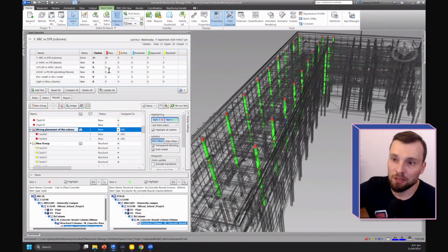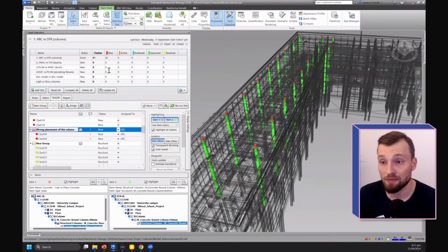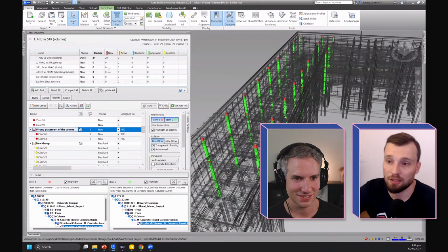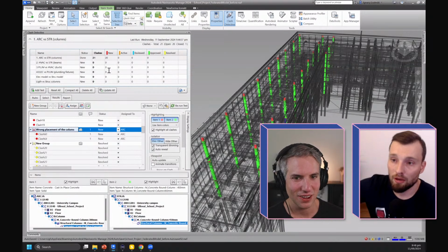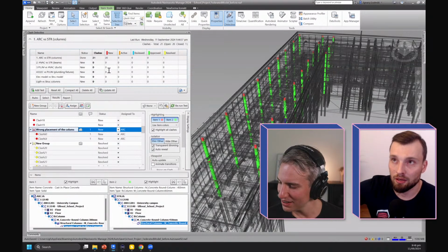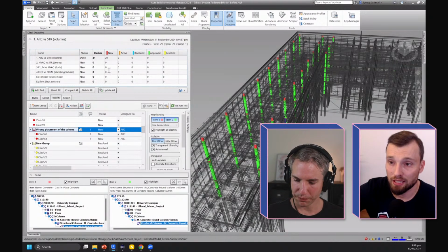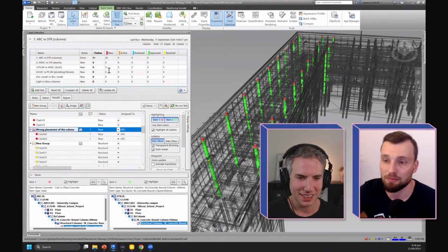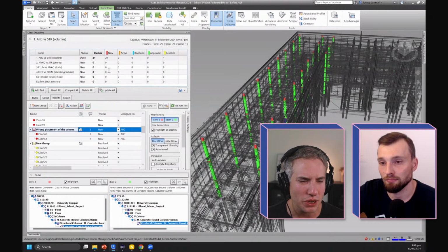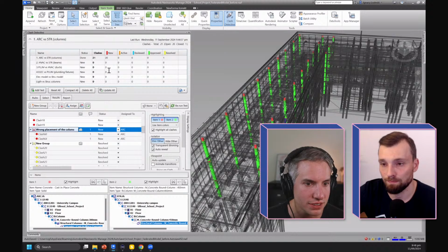That's why we also run data coordination of the model, just to check if elements are in the right IFC classes. And I'm going to show how to do it in Solibri in this presentation as well. So first we are checking if the models have the right category, and then we perform the clash test. Okay, we're going to see that.